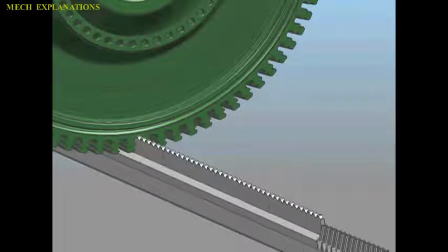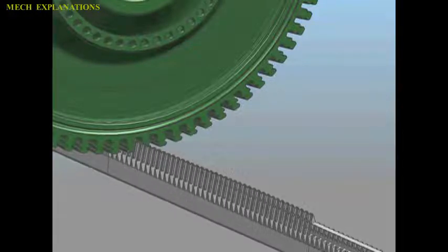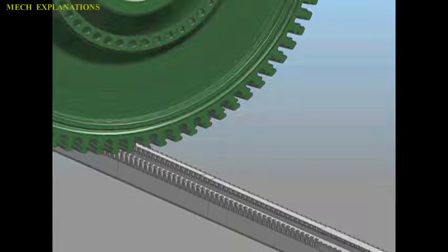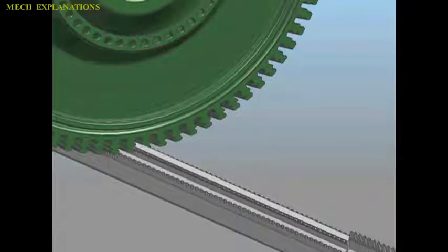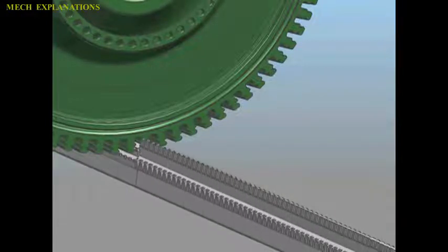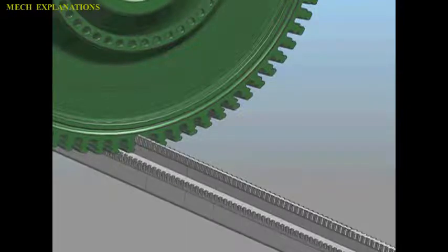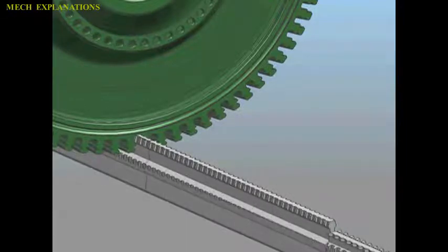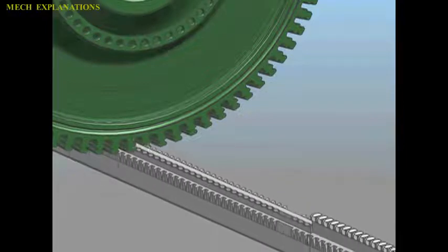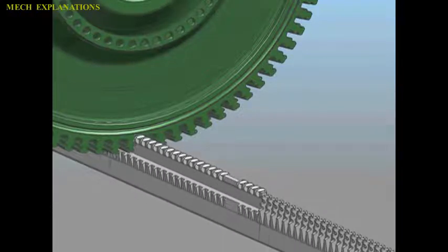Because all of the features are built into the broach, no complex motion or skilled labor is required to use it. A broach is effectively a collection of single-point cutting tools arrayed in sequence, cutting one after the other. Its cut is analogous to multiple passes of a shaper.